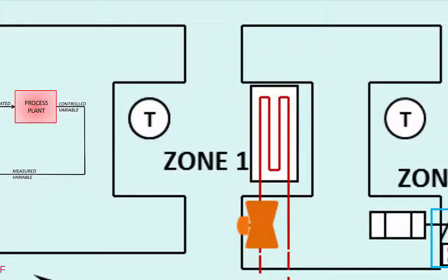The first would be auxiliary heating units. These could be a hot water baseboard radiator located along the exterior wall of a space, or they could be a fan coil unit. Those two are just heat exchangers. They are expelling heat from the hot water loop directly into the air in the space.